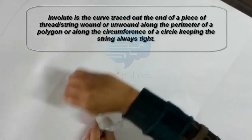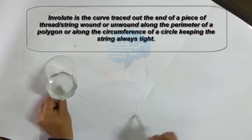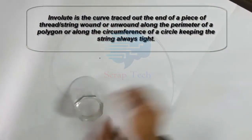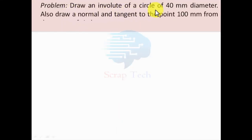Well, it is the curve traced out by the end of a piece of thread wound or unwound along the perimeter of a polygon or along the circumference of a circle, keeping the string always tight. Now let's understand this with the help of a problem. Draw an involute of a circle of 40 mm diameter. Also draw a normal and tangent at a point 100 millimeters from the center of the circle.